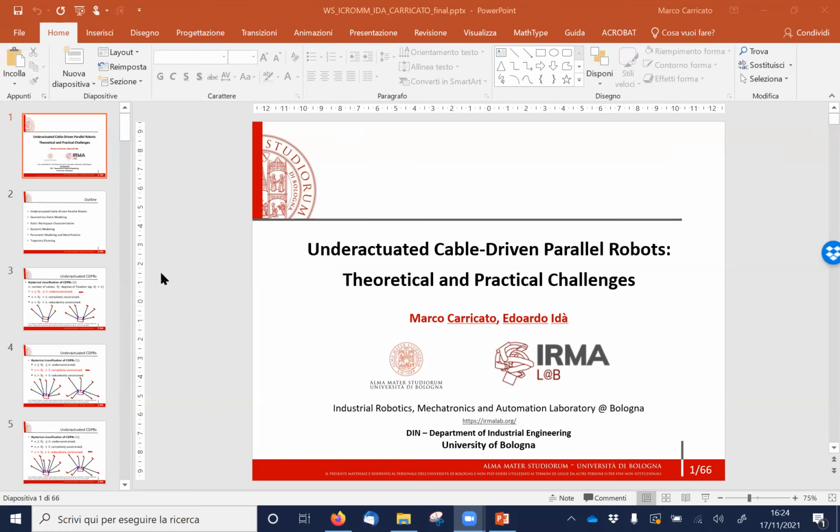So would there be benefits of having other sensors involved? Oh, definitely, definitely. There can be several sensors that can be considered. The easiest and the cheapest are probably sensors on the pulley that give us extra information about the orientation of the final pulleys that guide cables into the workspace. They are probably the cheapest and the simplest to implement, but they are not the most robust, because there is really nothing that constrains the cable to remain on the pulley plane.